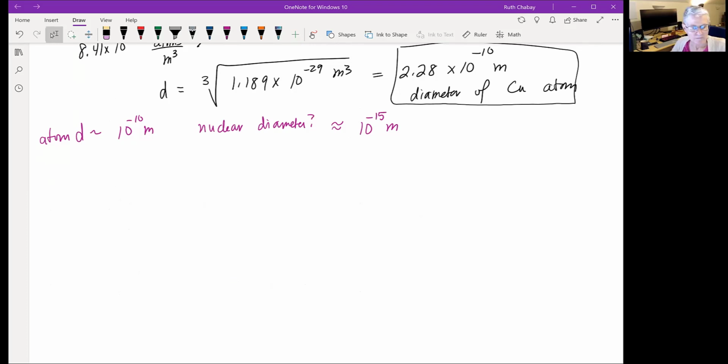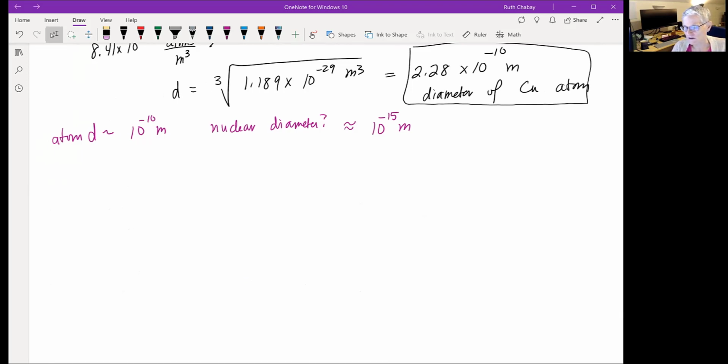So now we know this. And so we know roughly how long one of these bonds is. In our ball spring model, this length here is about 10 to the negative 10th meters, the length of a spring. So it's clear that any individual bond isn't going to stretch or compress by very much, but when we have a lot of atoms, that can add up, and if they all stretch, we're going to get significant deformation.